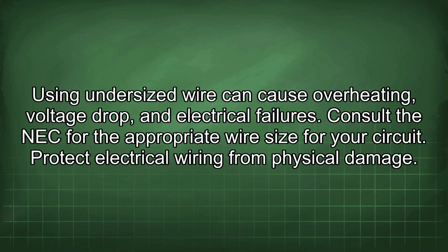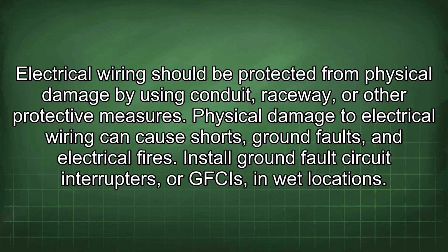Protect electrical wiring from physical damage. Electrical wiring should be protected from physical damage by using conduit, raceway, or other protective measures. Physical damage to electrical wiring can cause shorts, ground faults, and electrical fires.